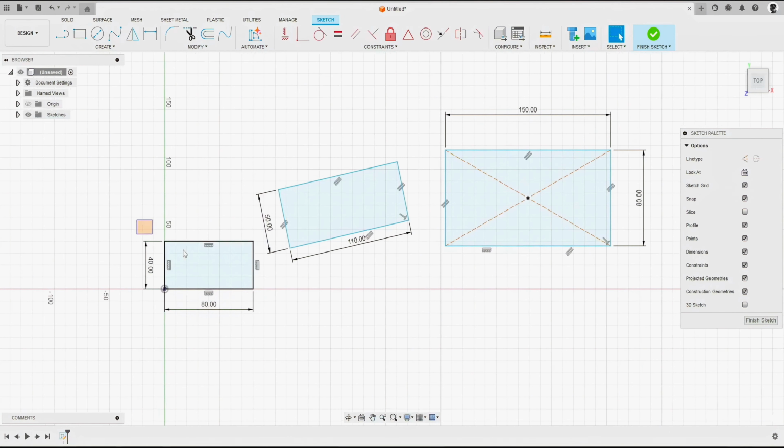Again, the most common is the 2-point rectangle. It sits right up here and it's the first selection when we hit R on the keyboard. And next most popular would be the center point rectangle. And then the third, and only for special cases, we do see 3-point rectangle. So we'll be using rectangles in the later examples, and I will see you in the next lecture.